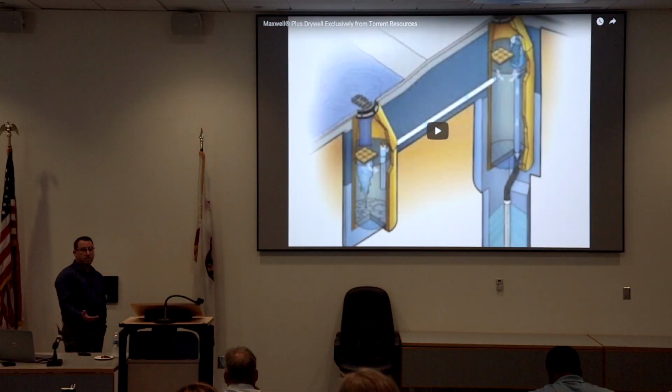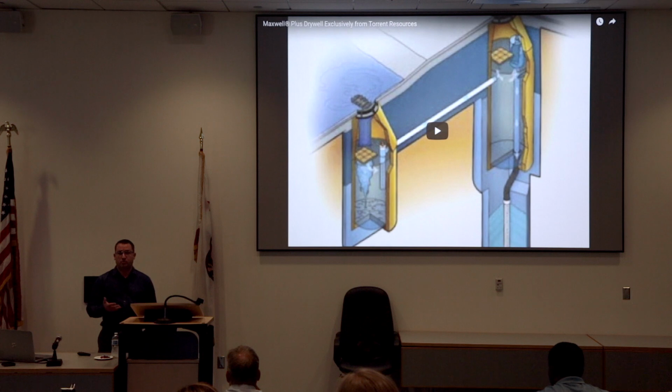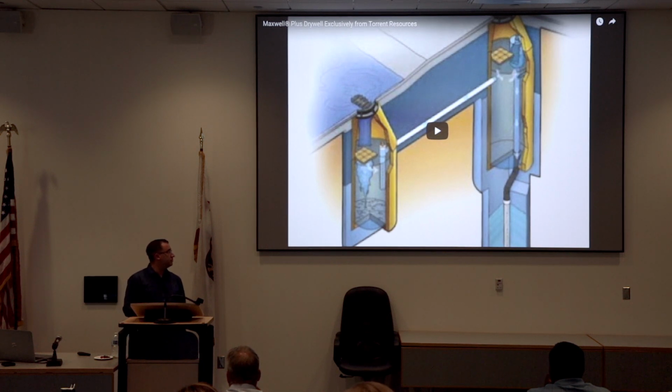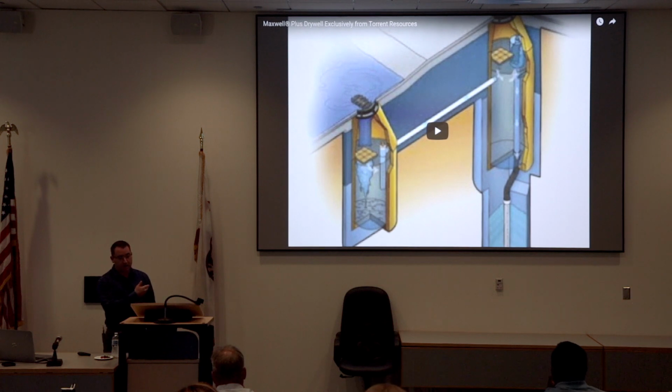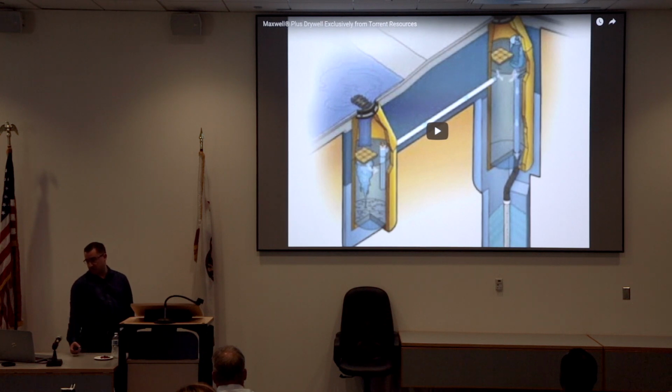So it's kind of simple, not a lot there, but that's a proprietary dry well device. David, before break, described their whole system of dry wells that they had on the government center site, which is another type of dry well. But this one's a proprietary device. It can work. You see how it functions. It's a two-step system where it fills up and then lets the sediment come out in the first dry well. We had a project that had a dry well on it, and I'll get into that a little bit later with lessons learned.